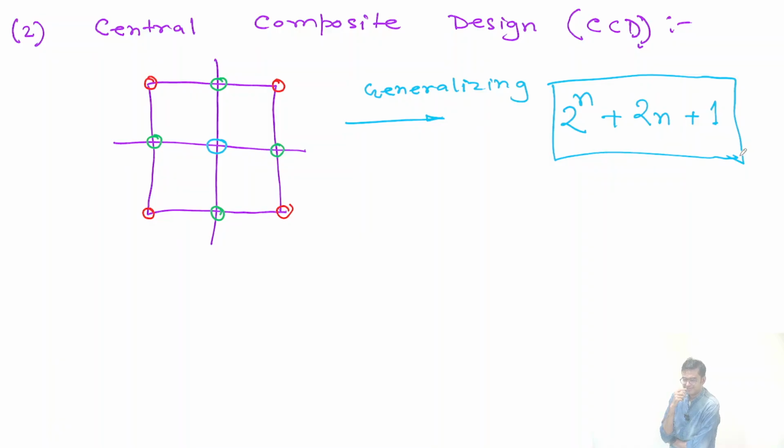Like here we can, there are 4 squares, right? So we put. But why do we take quadrature points? What is the use of quadrature points we have covered in this course? Can you tell me? We can use it for interpolation. No, quadrature point is used because we solve the integration numerically. Why am I taking? No, that I am coming to later. So there is a motivation behind the quadrature point in FEM because there is an integral problem you are solving, and in integration you are going to do it numerically, and if you do it numerically, you look into the convergence of this